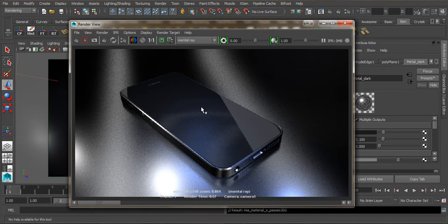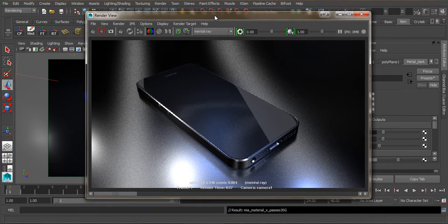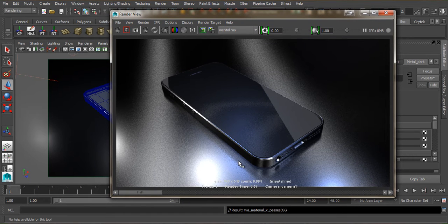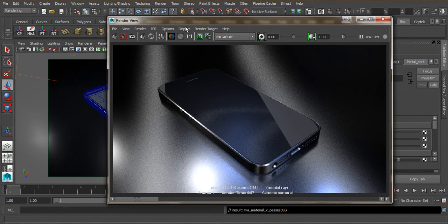So let's go ahead and up the render settings if you're completely happy with the view. This may be a good time as well if you're animating the camera to get that set up while the settings are still at this quality, and make sure that the beginning and end frames are something that you're happy with, and then go ahead and batch render that. Obviously there's separate tutorials on how to do that. For now, let's go and get these render settings done.